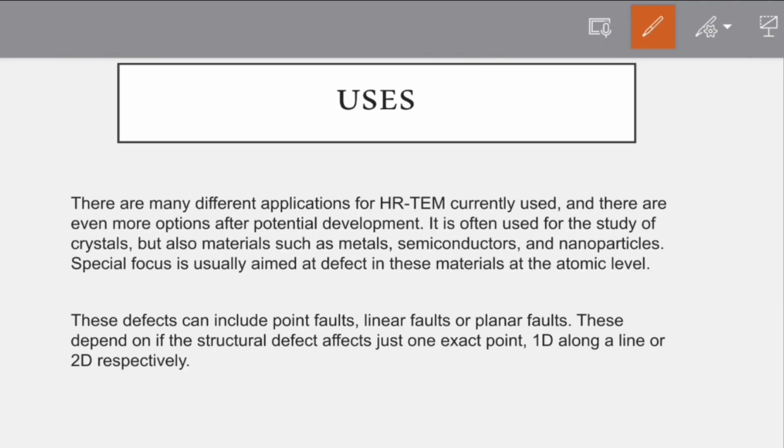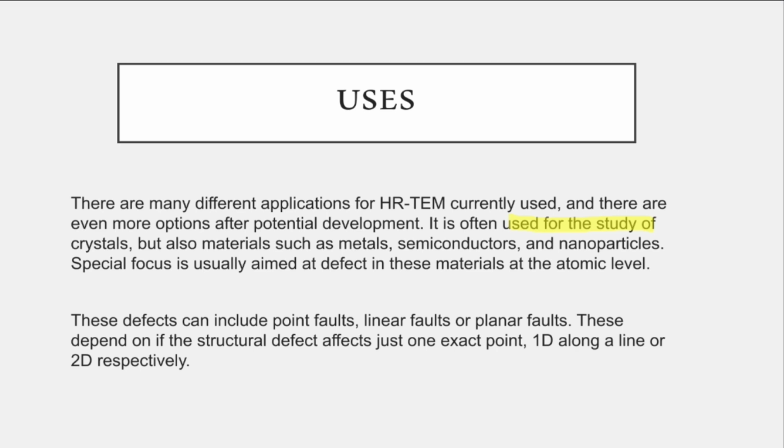Now the uses of HR-TEM. HR-TEM is often used for the study of crystals, but also materials such as metals, semiconductors, and nanoparticles. Special focus is usually aimed at defects in these materials at the atomic level. These defects can include point faults, linear faults, or planar faults. This depends on whether the structural defect affects just one exact point, 1D along a line, or 2D respectively.